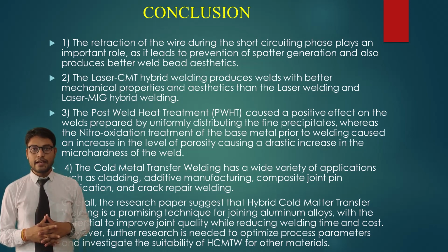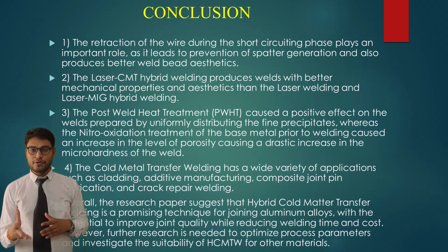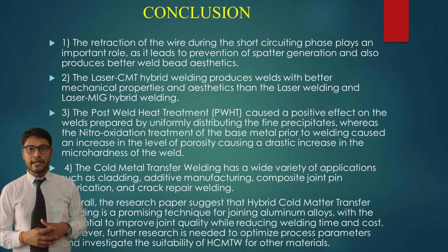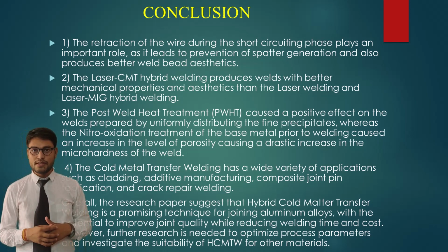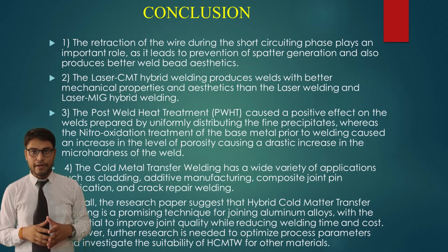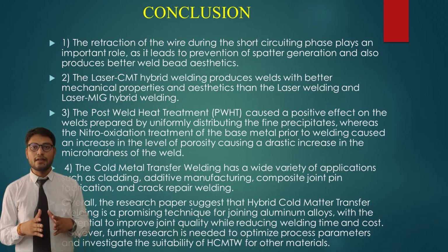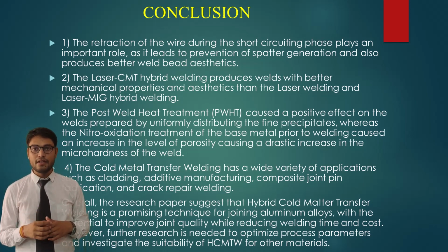Second, laser CMT hybrid welding produces welds with better mechanical properties and aesthetics than laser welding and laser MIG welding produce. Third, post-weld heat treatment has a positive effect on the weld by uniformly distributing fine precipitates, whereas nitro oxidation treatment of the base metal prior to welding caused an increase in the level of porosity, causing a drastic change in the micro hardness of the weld.